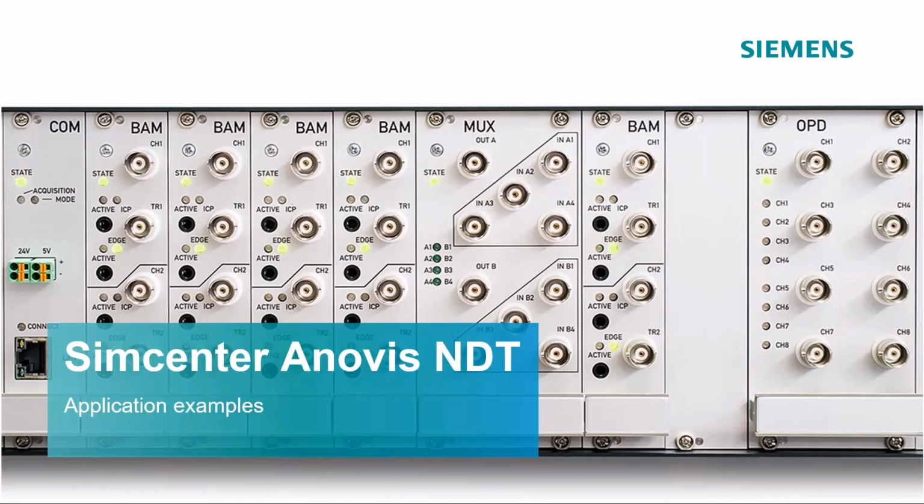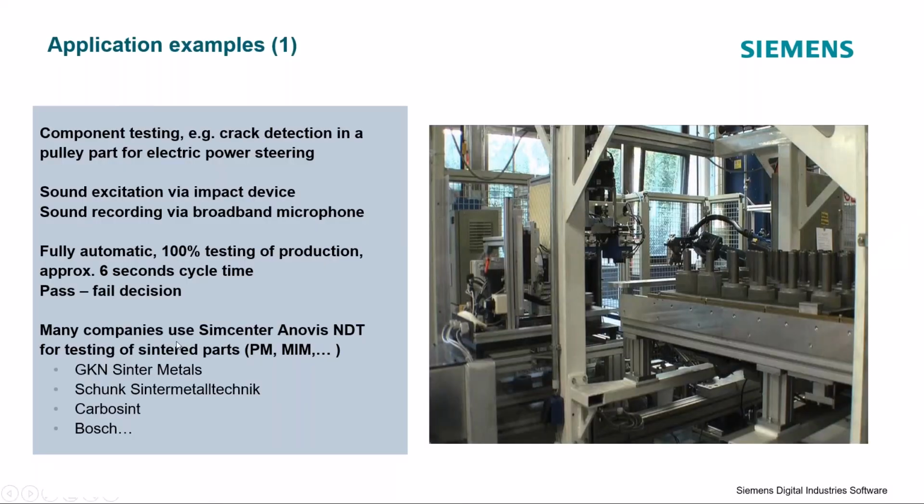Now we are at the last point: the application examples. Maybe the most interesting because everybody wants to see how it works and what it looks like. For example, crack detection in a pulley part for electric power steering. It's a safety relevant part. All of them have to be tested. We get the sound by hitting the part with an impact device, and the recording is via broadband microphone.